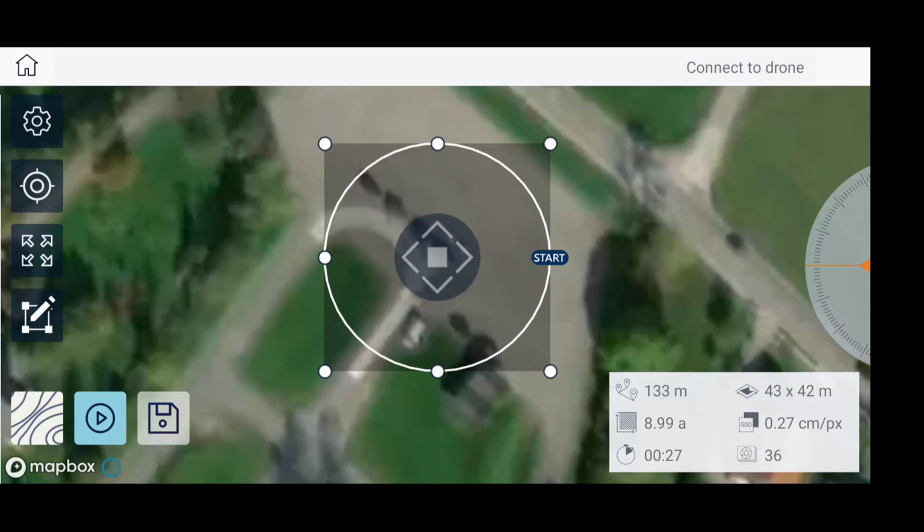So we advise you to start with the highest circle at 20 meters, then go to 50 meters, and then even lower, 10 meters. And this is the best approach to get an accurate 3D model. So this is everything about the planning in the 3D Survey Pilot app. Let's go now to the office and see the results from the field.